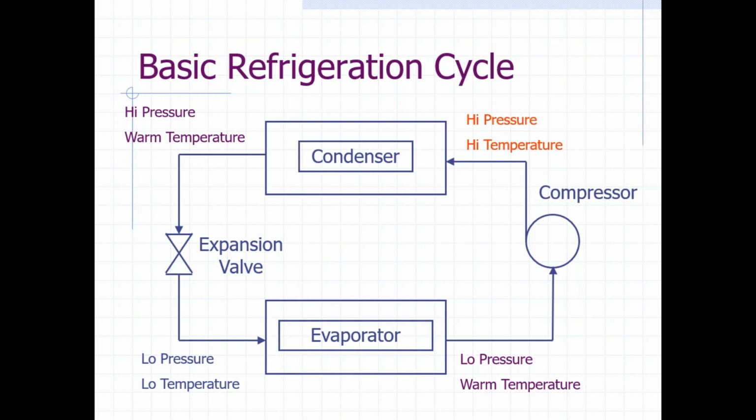Basically, how it works is, I'll start with the compressor. There's this line that goes through everything. You'll see this pointed line that goes through these different units: the compressor, condenser, expansion valve, etc. If we start with the compressor, what does that do? It compresses. There's a refrigeration fluid, a refrigerant, that goes through those lines. The compressor compresses or adds pressure to that fluid, and when things get put under pressure, their temperature goes up. It's just a basic thermodynamics law.